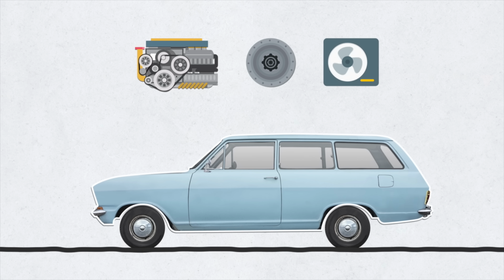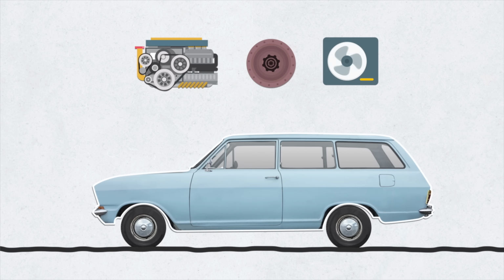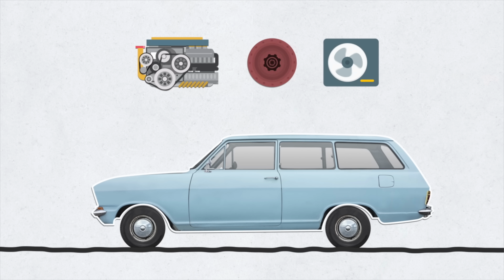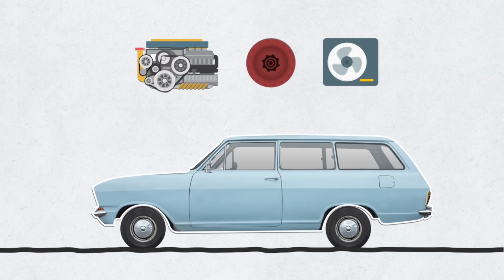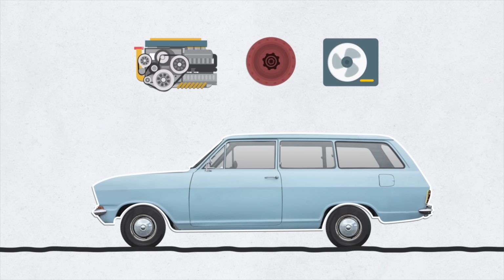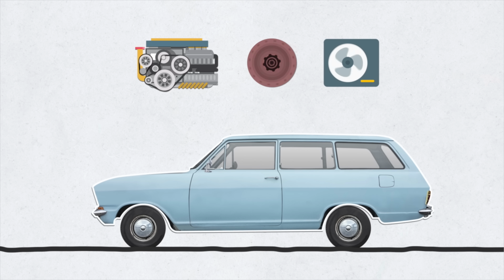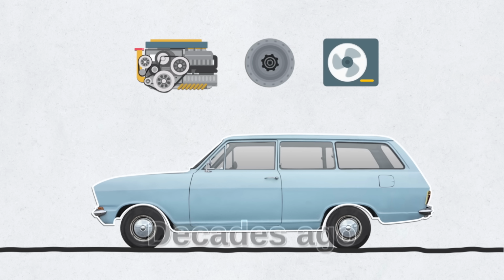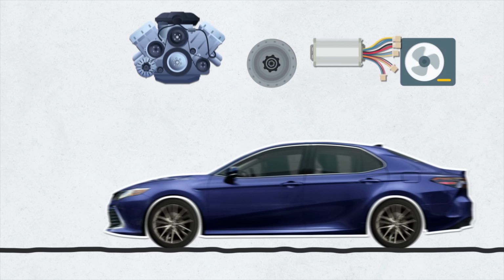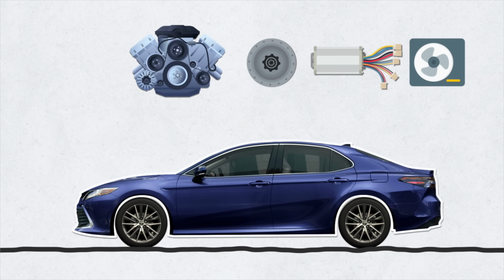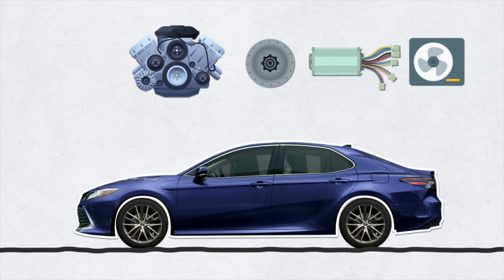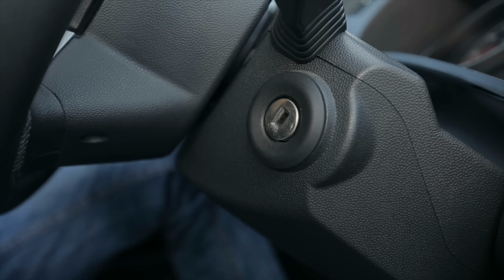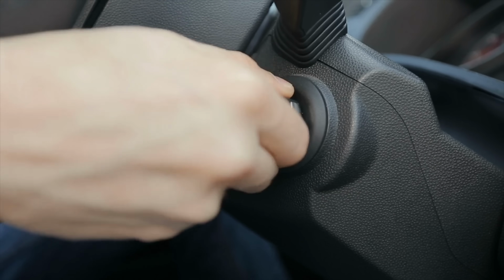Some people believe if you turn on the engine without shutting the AC off, the AC's compressor will face a massive power load on startup, and that repeatedly starting the car with all the systems on will ultimately shorten its life. Well, that was true with older cars with carburetors decades ago. But nowadays, with modern cars, that's no longer the case, because modern cars have air conditioning units that are designed to shut off automatically when the starter is engaged. So for this reason, we can say that is a myth.